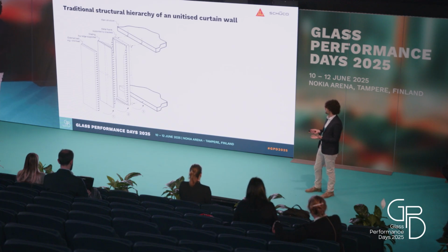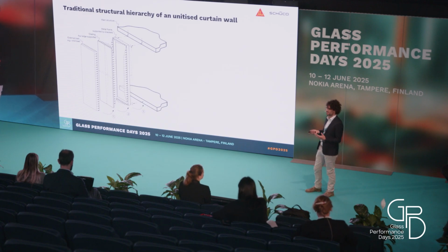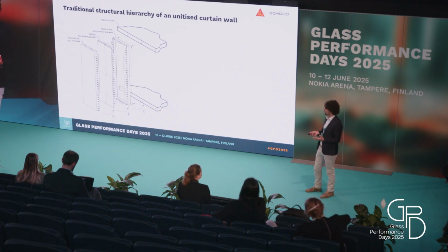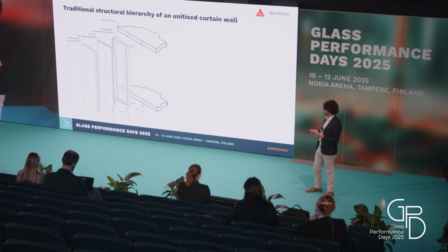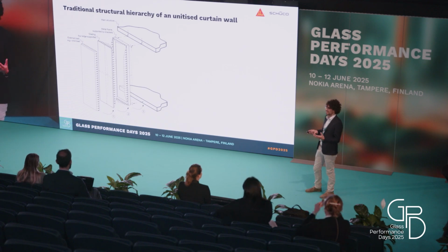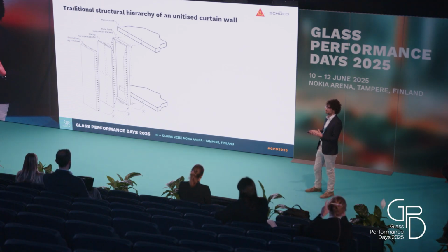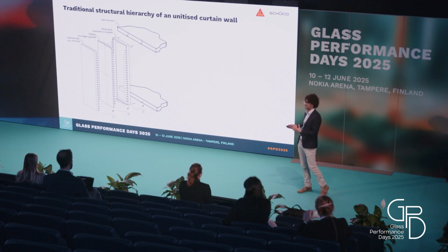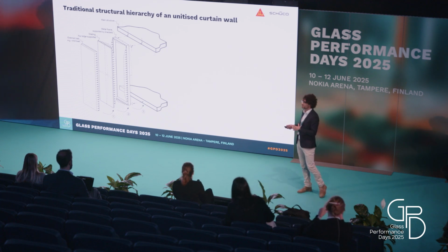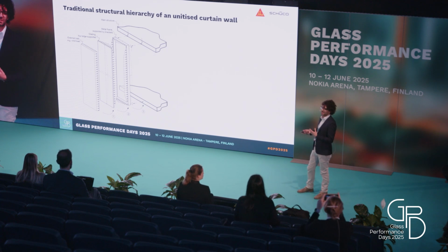We realize profiles for facades, and like most of the unitized facades nowadays, it's not always the case, but most of these, for out-of-plane loads, are designed in such a way from a structural point of view that the wind load, so the out-of-plane load, is taken directly, fully by the aluminium. Then you design most of the time the glass as an infill panel.